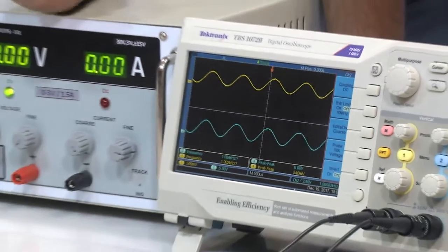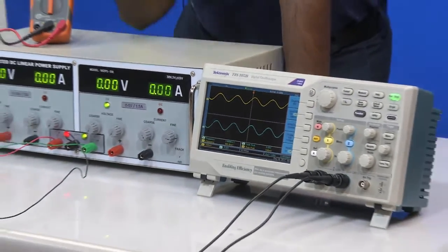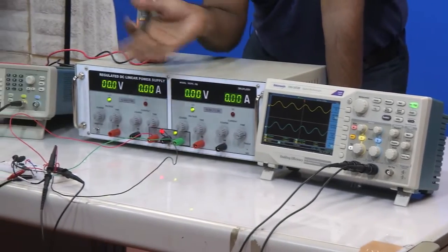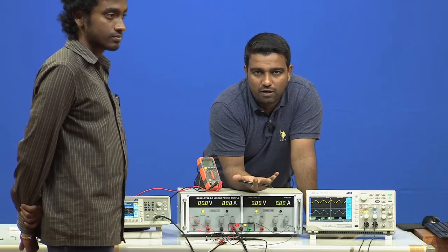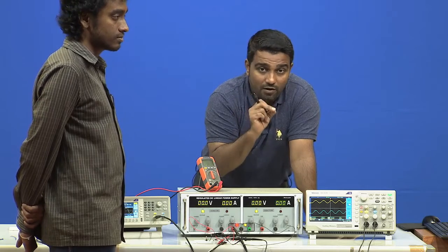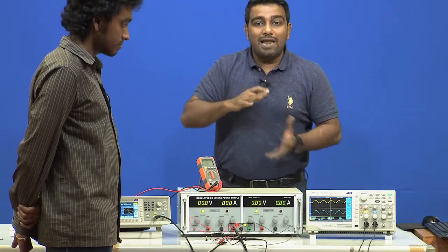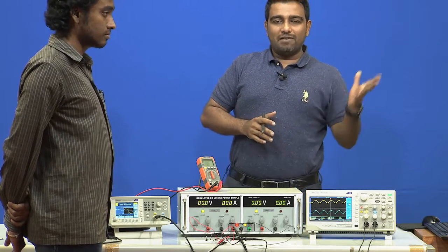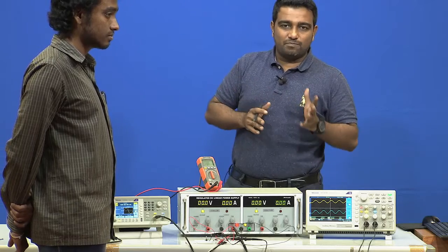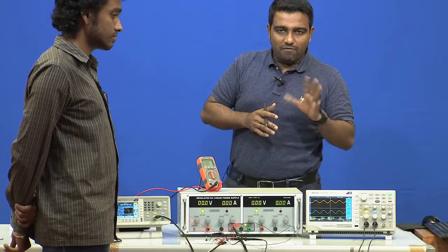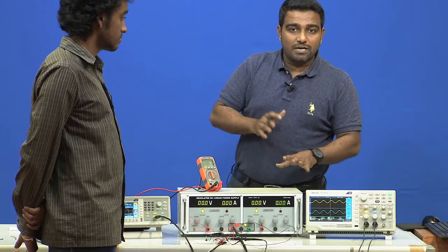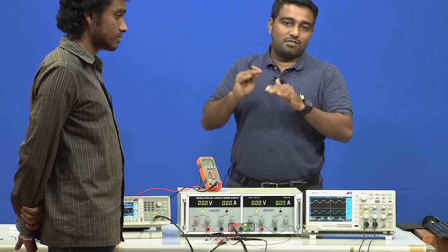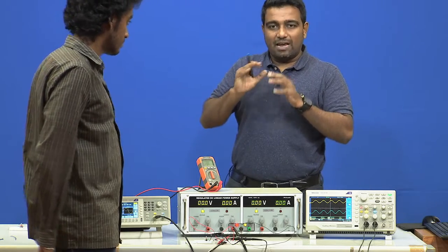This depends on your gain. So, do not forget, if you set a gain extremely high, then even 0.5 will be beyond your voltage range. So, anything below 0.5 only you can use as an input voltage range. So, that depends on your gain, alright. If I keep my gain around 11, then 0.5 times 11 would be somewhere around 5.5, right. So, it will give us approximately 6 volts, because I told you last time of the resistors mismatching, the values of the resistors are not accurate, that is why.